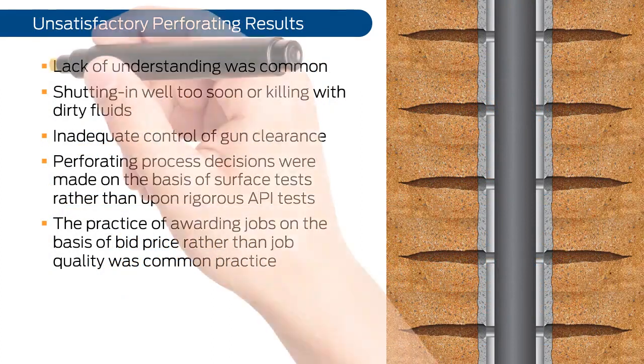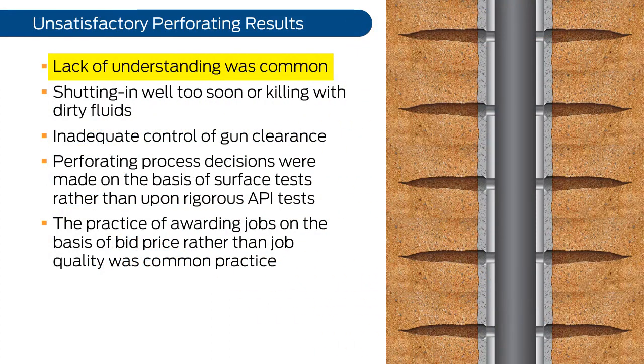In addition, there was a lack of understanding of the overall perforating process. Little was known about the positioning of the gun in the well, gun clearance, and related decisions regarding other perforating engineering factors.